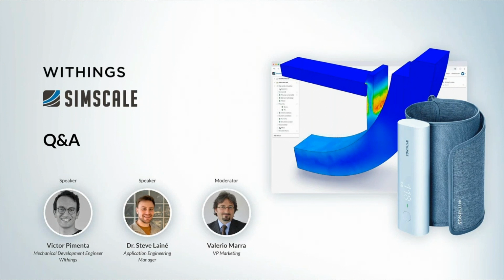So all its nodes, from the physical contact definition, to avoid any overlap, to ensure that the mathematical calculations succeed, we define, for instance, all the surface from the plastic casing in contact with the PCB as these slave surfaces. Got it. Thank you.